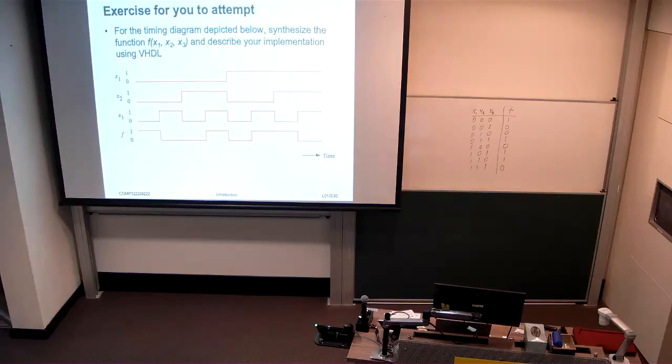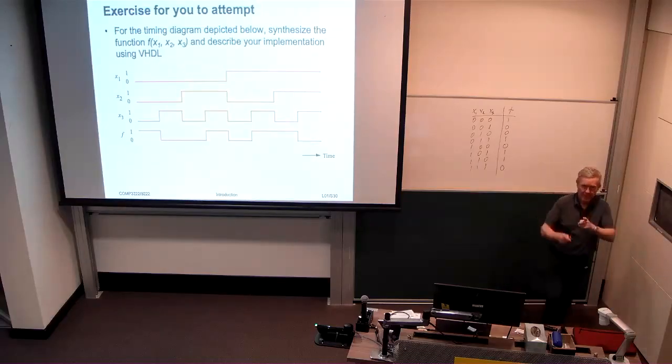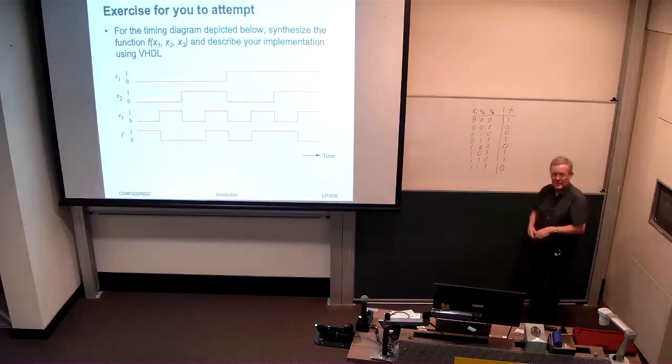I'm just having a look at the table. I don't know how right this is. If x1 is 1, the result is the XOR between x2 and x3. If x1 is 0, then it's the not of the XOR between. Right. Very good. Yes, all of you are correct, although the latter 2 speakers are right, and I don't believe them that they've never done any logic design before. For the rest of you, you're being honest about not having done it, or you're too shy.